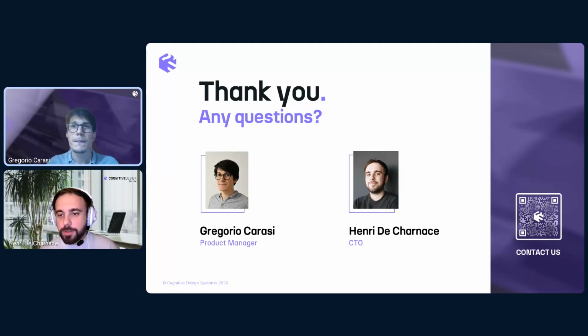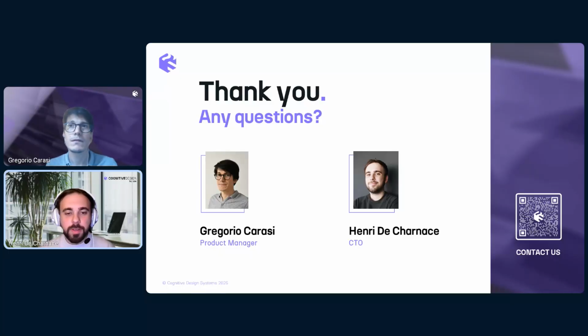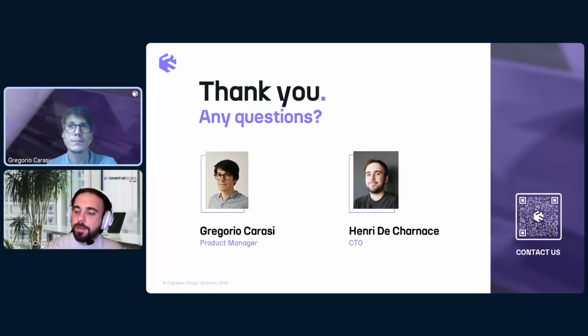Okay, so we have another question. So about the remote force vector, can we automatically set it to the normal to the selected CAD surface? So right now, there is no such option. So you have to put yourself the direction as a vector. However, if you use a pressure, for example, you can have a normal force to any point on a surface. It's interesting feedback.